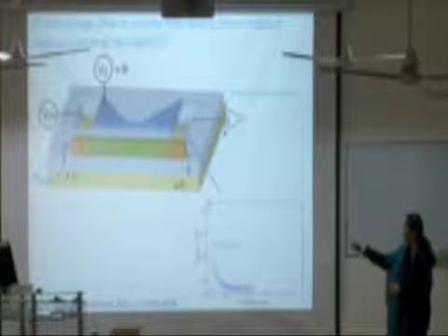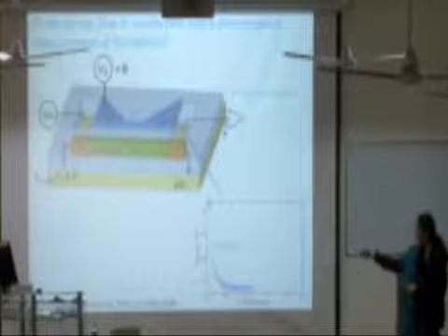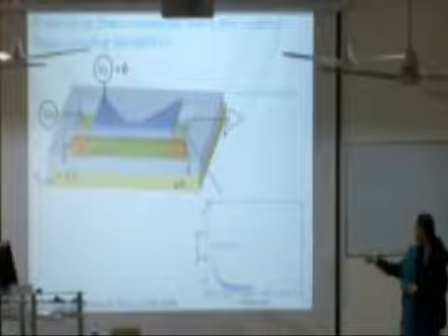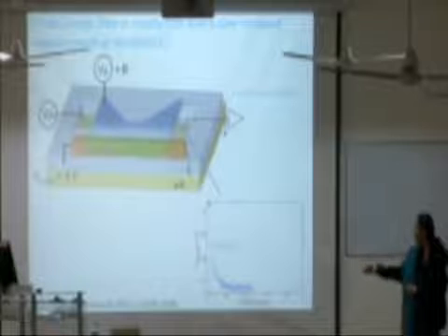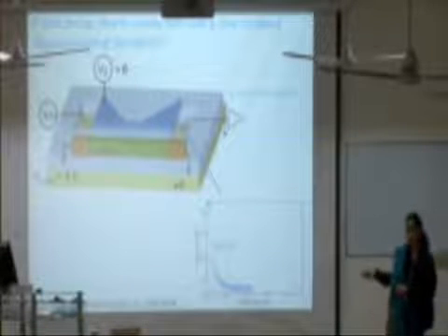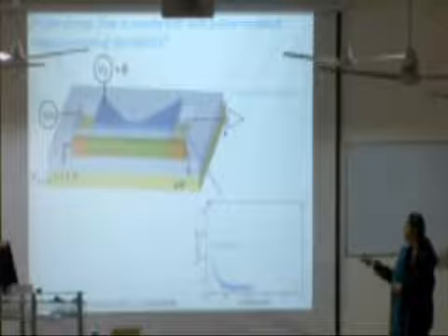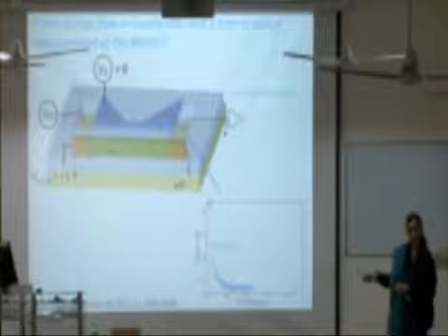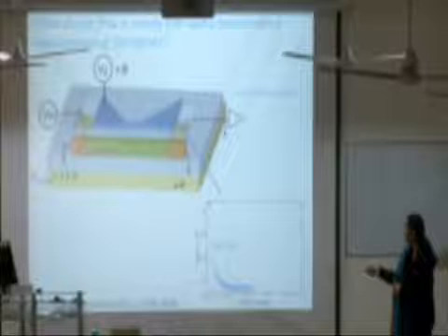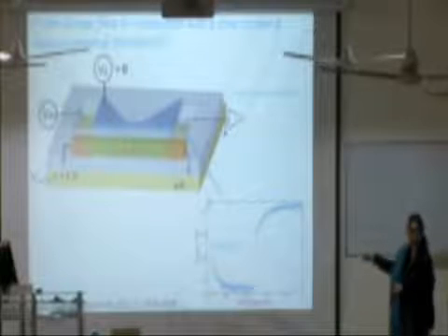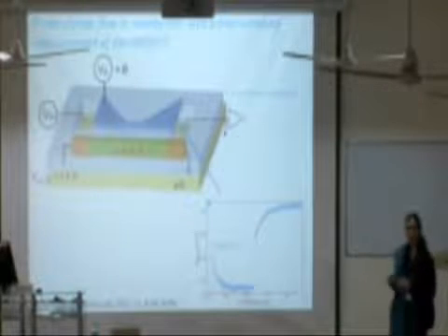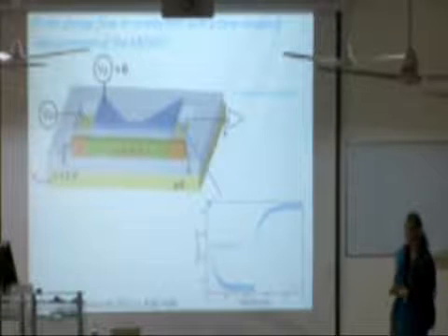What we see is that when we apply a negative voltage pulse, pulsing from 0 to -1 volts, we see first a rapid response, and then a slow decay of the conductance of the MOSFET, which can be fit very well to an exponential. And then when we pulse it back, going down from 0 to -1 volts and then back up, we see a response which goes the other way. We can fit exponentials to both of these and extract the RC charging time constant.